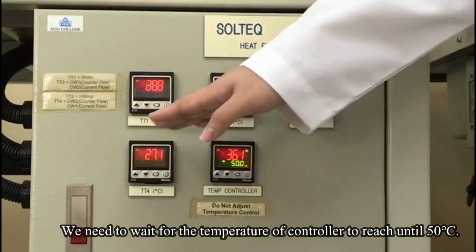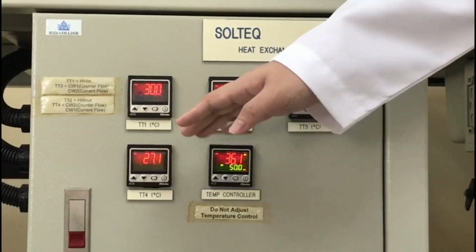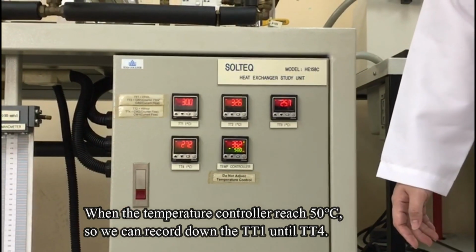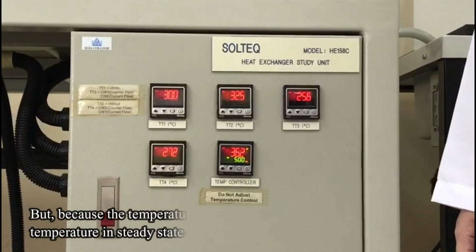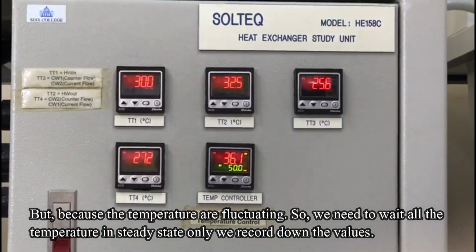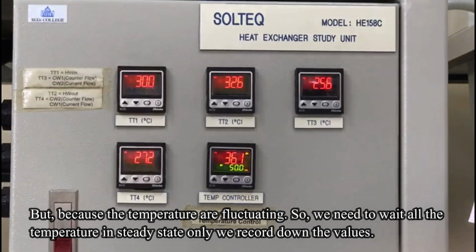We need to wait for the temperature controller to reach 50 degrees Celsius. When the temperature controller reaches 50 degrees Celsius, we can record down TT1 until TT4. But because the temperatures are fluctuating, we need to wait until all the temperatures are in steady state, and only then do we record down the values.